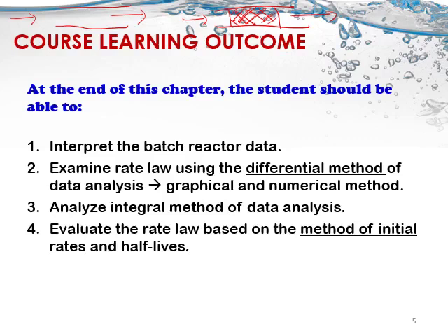Okay, and then the main difference is when it's PFR, we are dealing with volume of the working fluid as reactant, or volume of the reactant, whereby for packed bed reactor, all the equations are similar except all V is replaced by capital W, that is weight of catalyst.